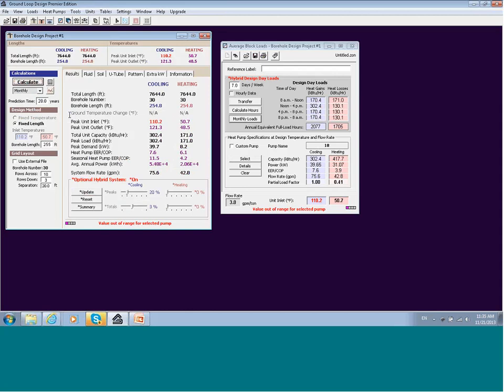And this is interesting. The monthly profile is basically telling me I have something to worry about here. The design day method, which we consider to be, in many cases, very straightforward, fast, using minimal data, sometimes it can miss things. The monthly design here is predicting that the temperature is really going to creep up to perhaps an unsustainable level. So based off of this information, I may decide, okay, I want more of a hybrid system.